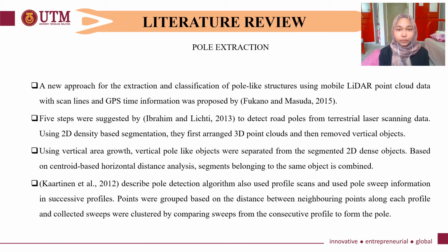Segments belonging to the object are combined, and the last one is the Cartesian pole detection algorithm, which also uses profile scans and pole sweep information in successive profiles. Points were grouped based on the distance between neighboring points along each profile, and collected sweeps were clustered by comparing sweeps from the consecutive profile to form the pole.